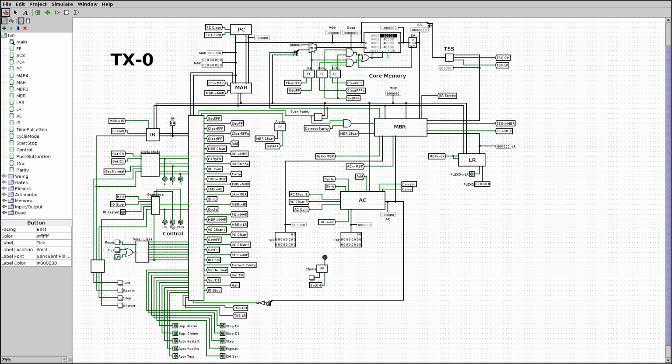And to synchronize the start and stop conditions from the I/O devices and the push buttons, we have two synchronized flip-flops, the I/O synchronized flip-flop and the push button stop flip-flop. And if any of these is a 0, that indicates that the machine is to halt, and if both of them are 1, that means the machine should be set running.